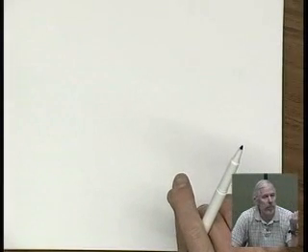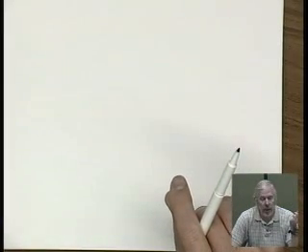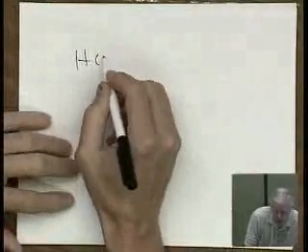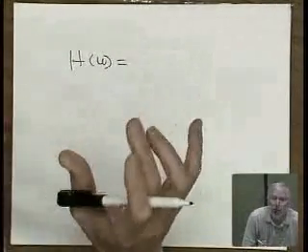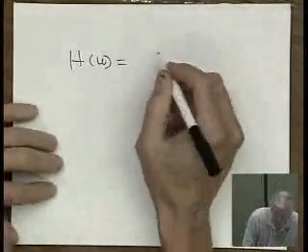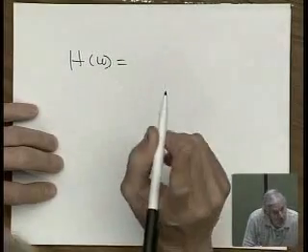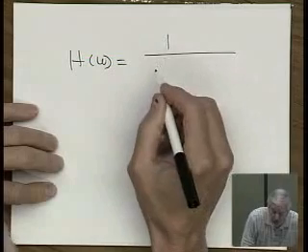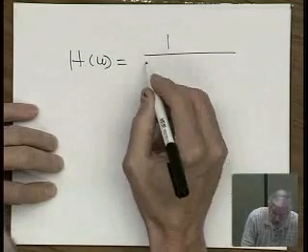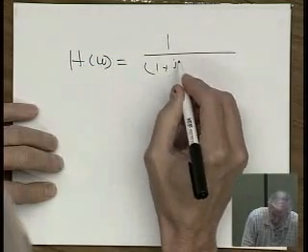It's for calculating the lowest frequency pole. It stems from writing down our transfer function, and it's called the zero value time constant analysis approach. It's only good for poles, and it's only good for the lowest frequency one. And so here's what it effectively relies on.